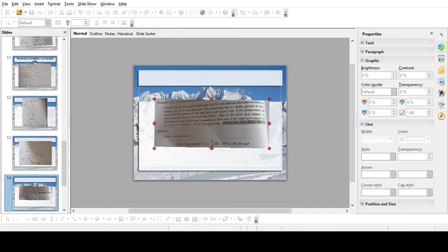The composite bar is rigidly joined at both ends. Find the stresses in the steel tube and the copper rod if the temperature of the composite bar is increased by 190 degrees centigrade. Take E for steel and copper as 210 kilonewton per mm square and 110 kilonewton per mm square respectively. Also take alpha for steel and copper as 11 into 10 to the power of minus 6 per degree centigrade and 18 into 10 to the power of minus 6 per degree centigrade respectively.